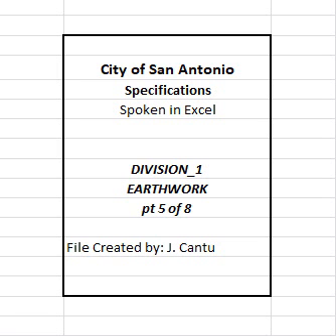E. Maintenance of moisture and reworking. Maintain the density and moisture content once all requirements in Table 2 are met. For soils with a PI greater than 15, maintain the moisture content no lower than 4 percentage points below optimum. Rework the material to obtain the specified compaction when the material loses the required stability, density, moisture, or finish. Alter the compaction methods and procedures on subsequent work to obtain specified density as directed.